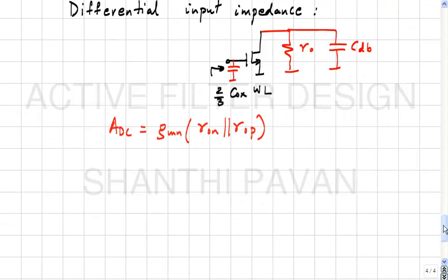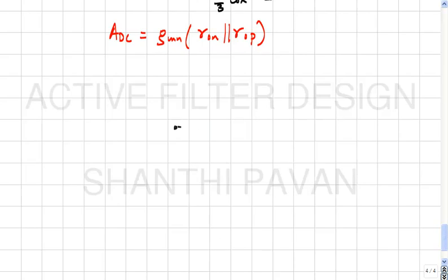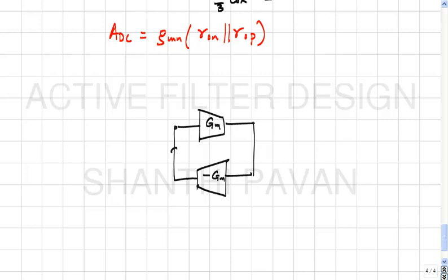Another thing I'd like to point out. When people draw gyrators and so on, they will always draw the single-ended equivalent because the differential equivalent is just extremely confusing without adding any new intuition, right? So when people say, this is the circuit diagram of the gyrator, even though they draw a single-ended equivalent, what it means is that in principle everything is fully differential. Just to avoid clutter in the diagrams, you always show the single-ended equivalent. So this is Gm, this is minus Gm. This is C.